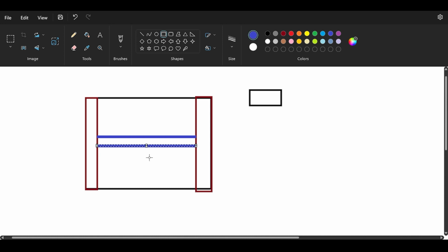Point number 2, I asked the architect to give me the slab to be on top of this beam if possible. I mean, if not possible, I can just break bricks, but that's what I usually do.